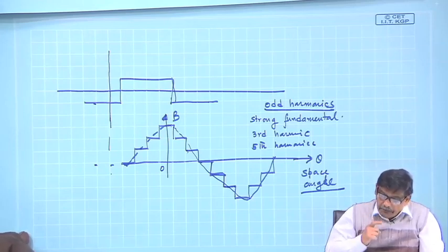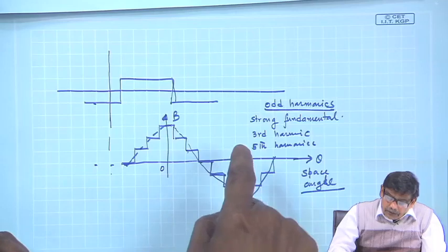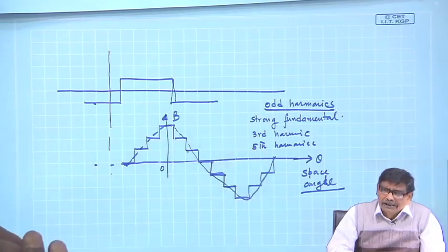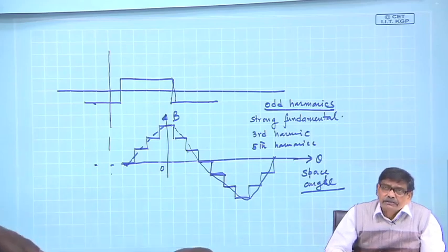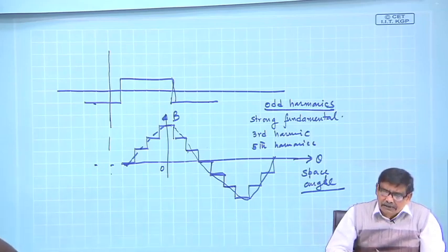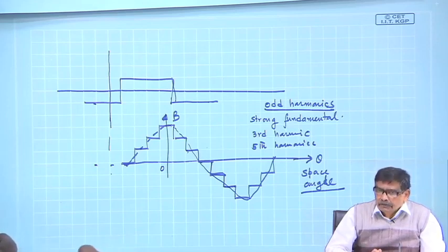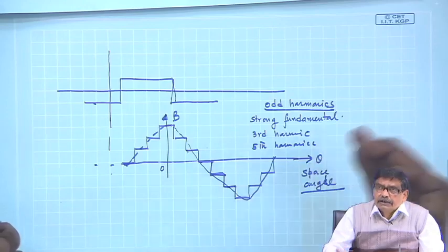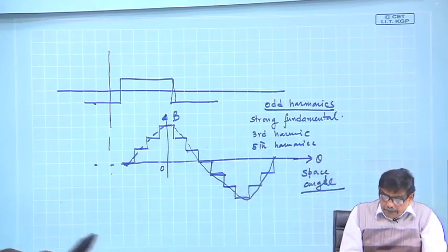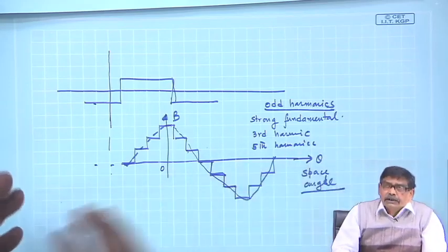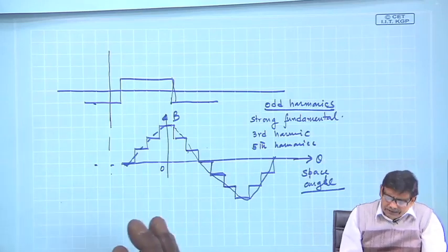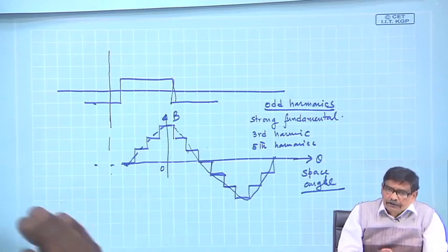But the point I want to make is, it is the question of predominant harmonic, whether predominant harmonic can be done away with by doing something tricky. We will show you this can be done. So, conductors, that I will discuss after few lectures, but the point is, better do not use a single coil, use distributed coils.